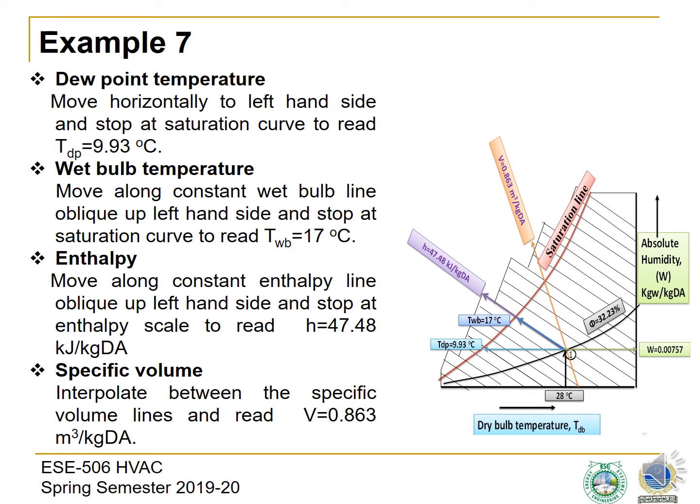We plot a state point on psychrometric chart and determine the other undefined parameters which we want to calculate from the psychrometric chart. This is the manual way of calculation, by locating a point with a pencil and then locating the other points and finding the other parameters.